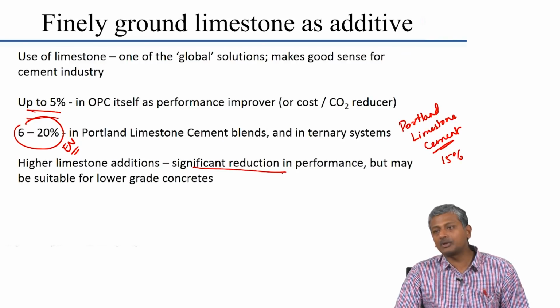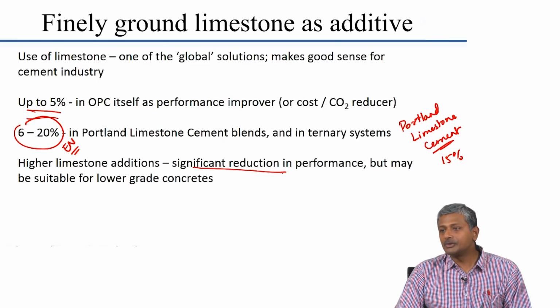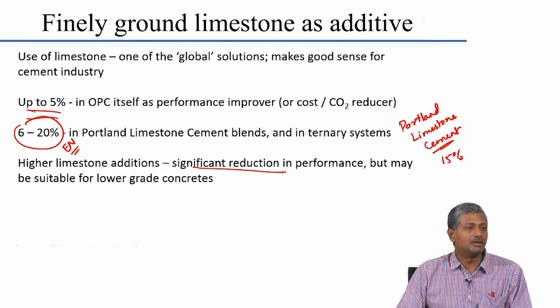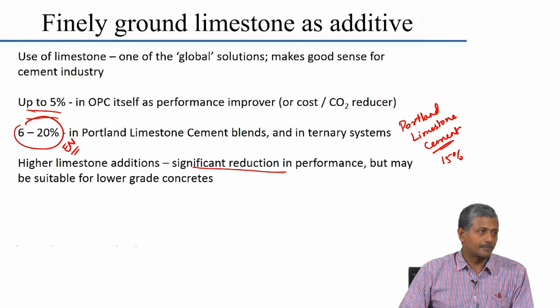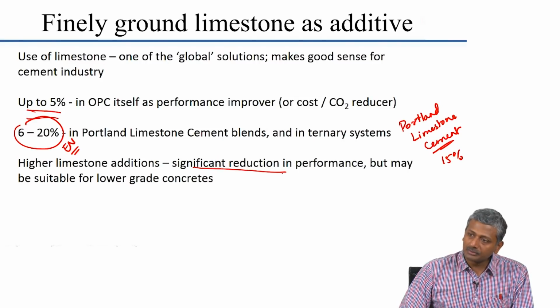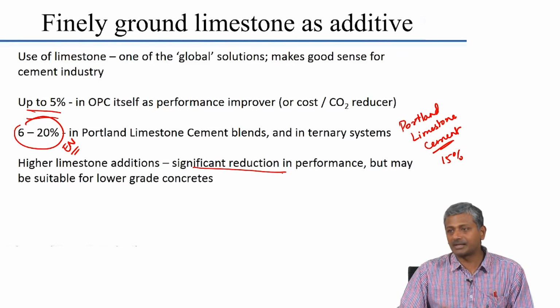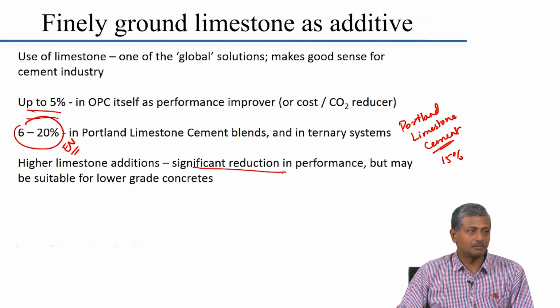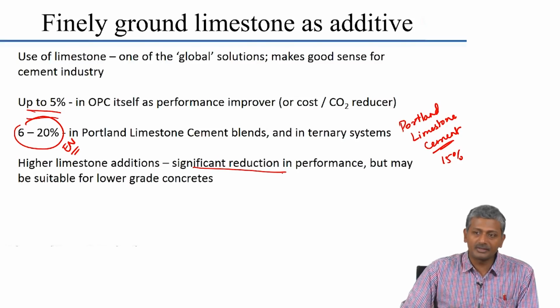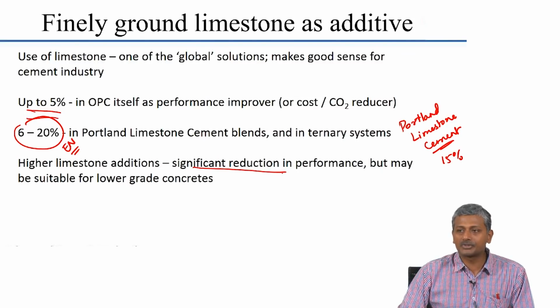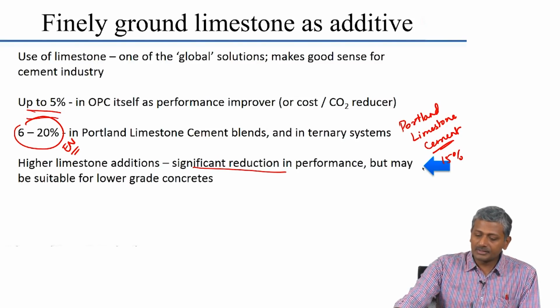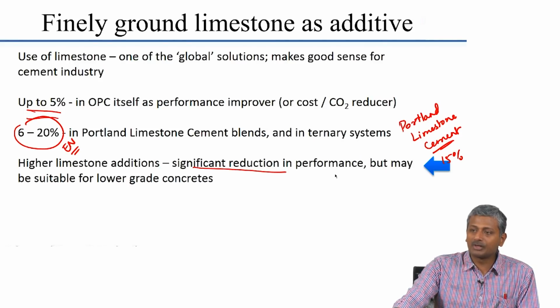When we see the next chapter on high performance concrete mixture design, you will see that the filler effect is able to some extent overcome the lack of reactivity that you see from most of these filler materials. If the material is both reactive and finely graded, then it provides much better benefits, obviously like silica fume or fly ash or slag. But with just fillers, you may get an enhancement only up to a certain level. Now, this of course is not very useful, so we will not look at this further.